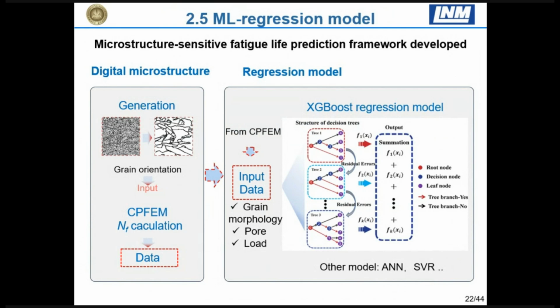We generate the digital microstructure using a machine learning method. And then we use the microstructure as an input for crystal plasticity analysis. Then we combine the methods altogether: a machine learning method for digital microstructure, crystal plasticity, and the fatigue lifetime prediction, the fatigue lifetime distribution. We are going to build this kind of framework.